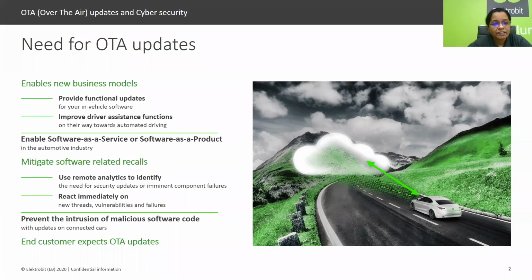The second advantage is that, with the ECUs and the system supporting over-the-air updates, this method could be integrated into the production process. Then the car's mechanical assembly could happen simultaneously with the ECU firmware update. Moreover, the up-to-date software could be installed onto the ECUs of the vehicle prior to delivery, irrespective of the vehicle's location. Also, this makes it possible for the OEMs to reduce the vehicle development lifecycle itself.